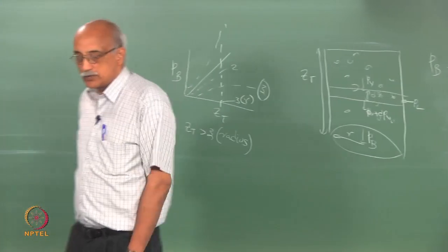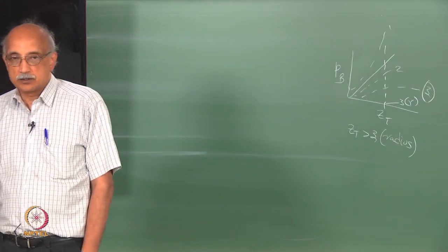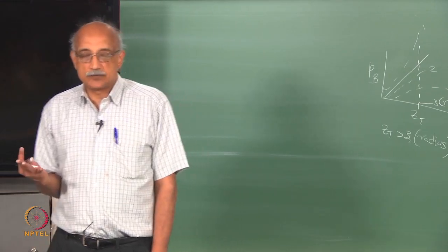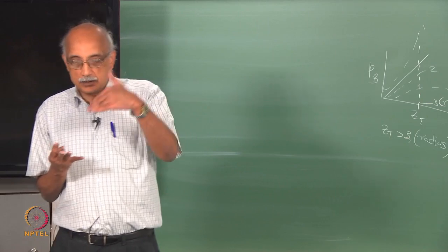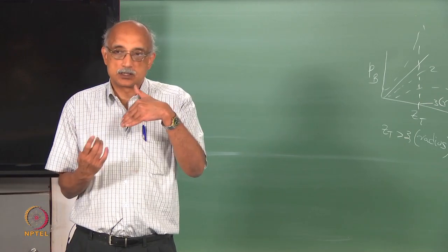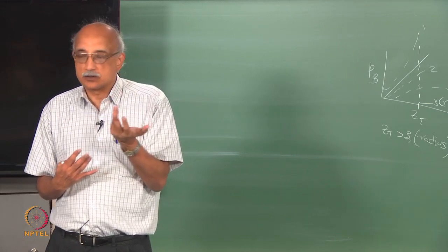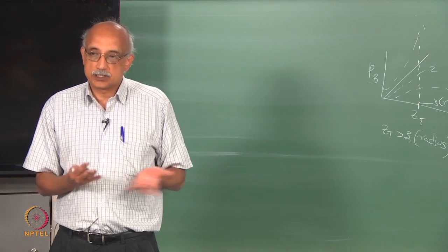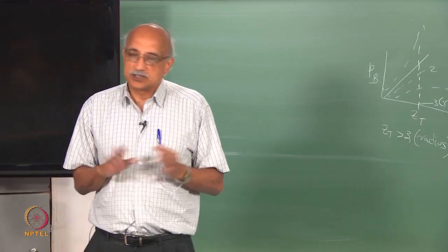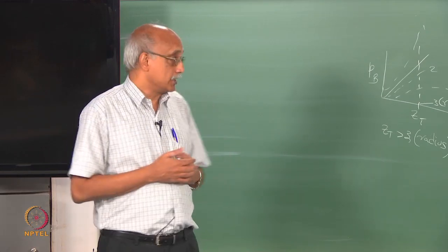The coefficient of friction is clearly a parameter here that you need to estimate, and the way you do that is by doing an experiment or by just observing at what angle do the solids that are in contact with the bin walls start to slide down, and if you take the tan of that angle, that gives you the skin friction coefficient. So, that is how you estimate mu prime. It is typically somewhere in the 0.2 to 0.35 kind of range.